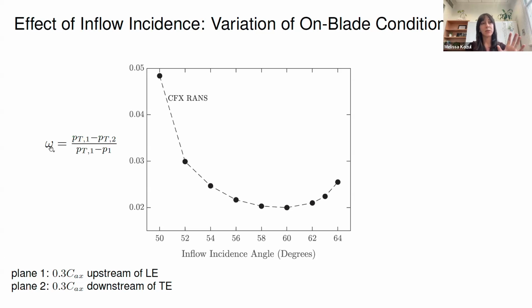Here we have what's called the stagnation pressure loss coefficient. Basically, it's a measure of efficiency. Lower is better. And happily, this was a study done by that modeling that I was talking about, that desktop type numerical simulation of fluid flow by our collaborators at GE. And they did this sweep, looking at different air angles coming into that compressor blade and what you get for the loss.